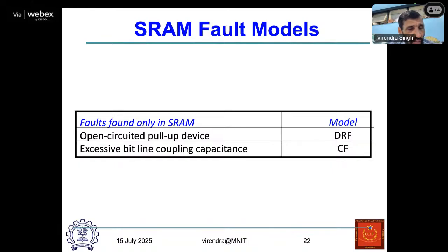Whereas DRAM is the dynamic random access memory, wherein you are storing data as a charge on a single transistor. Because that's very compact, we can have a large amount of memory available, so the DRAM size is something like a few GBs.